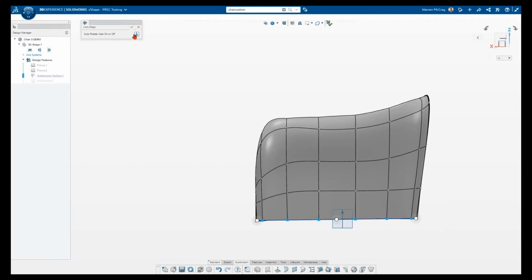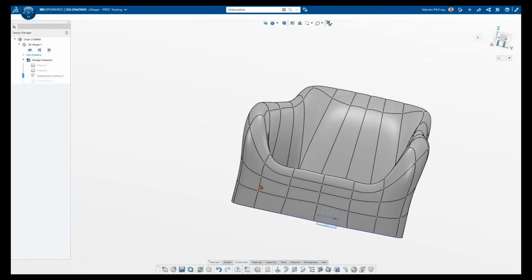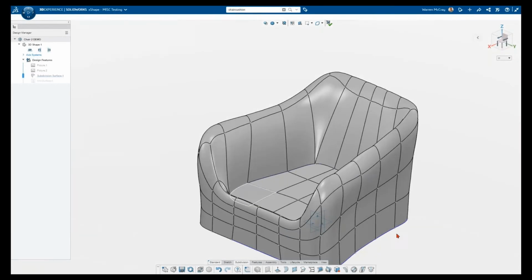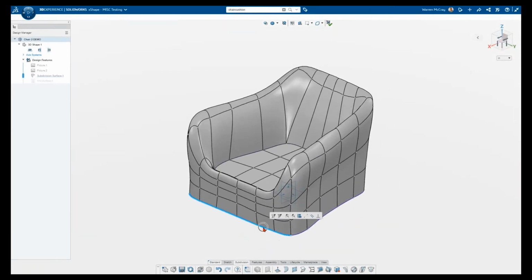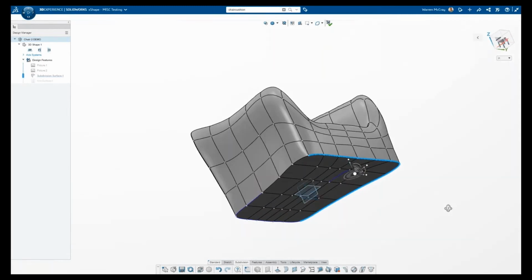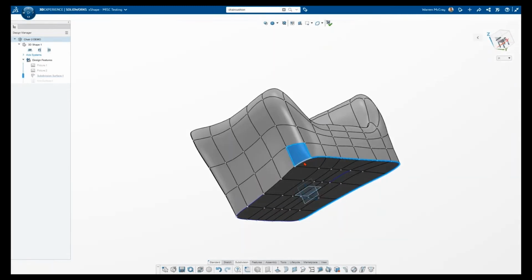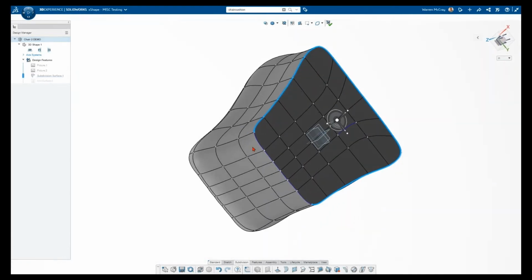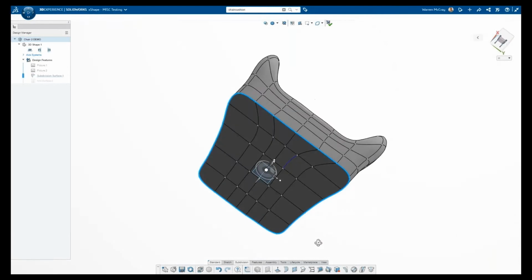So as you see, as I'm doing this, I'm adjusting, I'm looking at it, I'm rotating it around, and they have this nice feature. If you double click on an edge, it'll work like SOLIDWORKS, how you propagate along tangent edges. That's what it's doing when I double click on it. It propagates until it comes to a point or something that's not perfectly tangent. And in this case, I'm grabbing those edges now that I got it fairly flat.